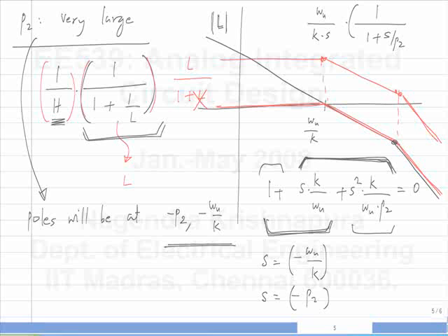So maybe in 0.18 micron technology, you will only be able to design op amps with maybe 1 gigahertz bandwidth or something, or feedback loops with 1 gigahertz unity gain frequency. When you go to a finer technology, in which all features are smaller, all parasitic capacitances are smaller, you can go to higher frequencies. Okay.